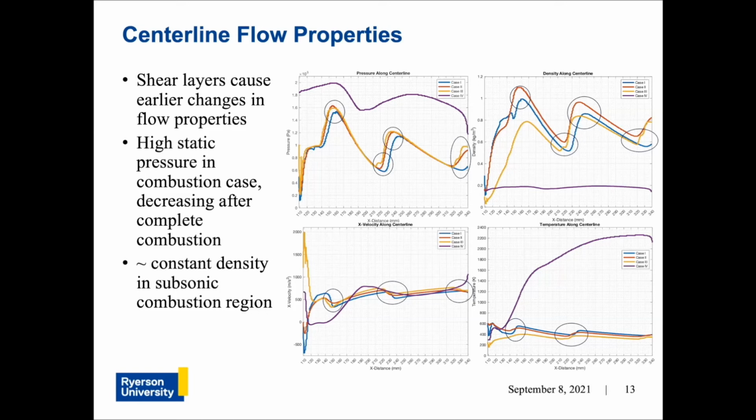The first inverse trend of this occurs when the low-pressure regions from the expansion fans join at the centerline, creating the shock diamond. The shock reflection after the expansion wave intersection with the shear layer creates the next high-pressure, high-temperature, high-density, low-velocity region. This pattern repeats until the combustor outlet, but diminishes with each successive shock-shear layer interaction as the waves lose kinetic energy.